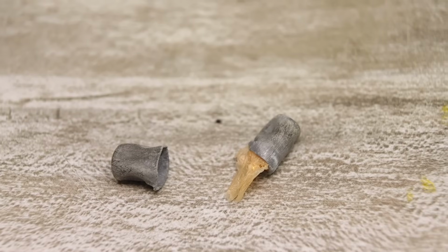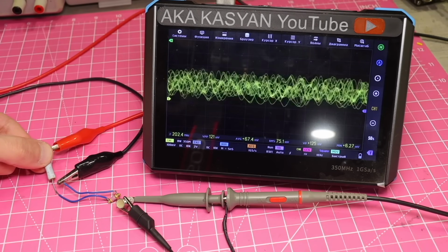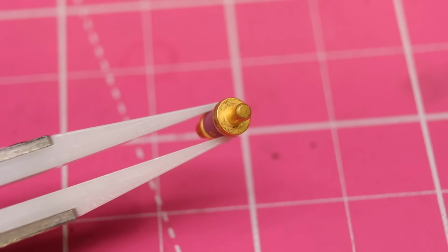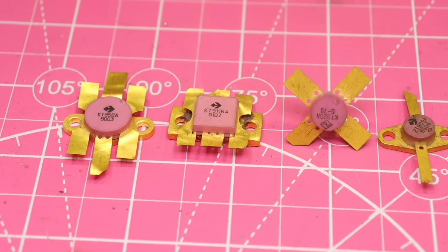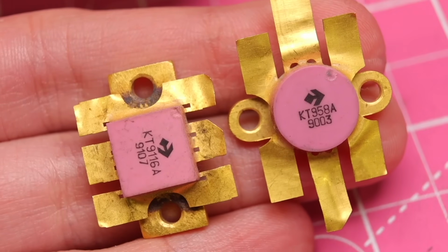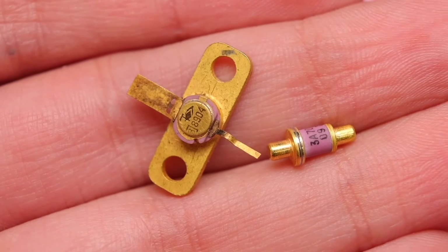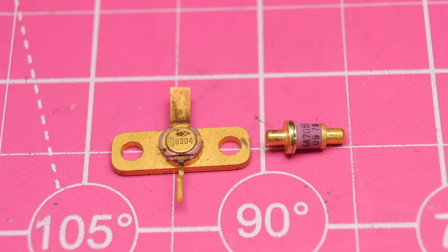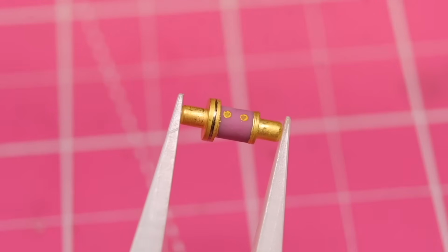The frequency of a Gunn diode is determined not by the circuit, but by the transit time of the domain through the active region of the crystal. This ensures a sufficiently clean spectrum and low phase noise in the range up to tens and hundreds of gigahertz. At very high frequencies, transistor efficiency drops sharply, gain decreases, parasitic capacitances dominate, and gate charge and discharge losses increase. The Gunn diode directly converts the energy of electron drift into an electromagnetic wave. The fundamental difference is that a transistor is a controlled electronic valve, while a Gunn diode is a moving domain of an electric field. It is the fields inside the crystal that create the oscillations.